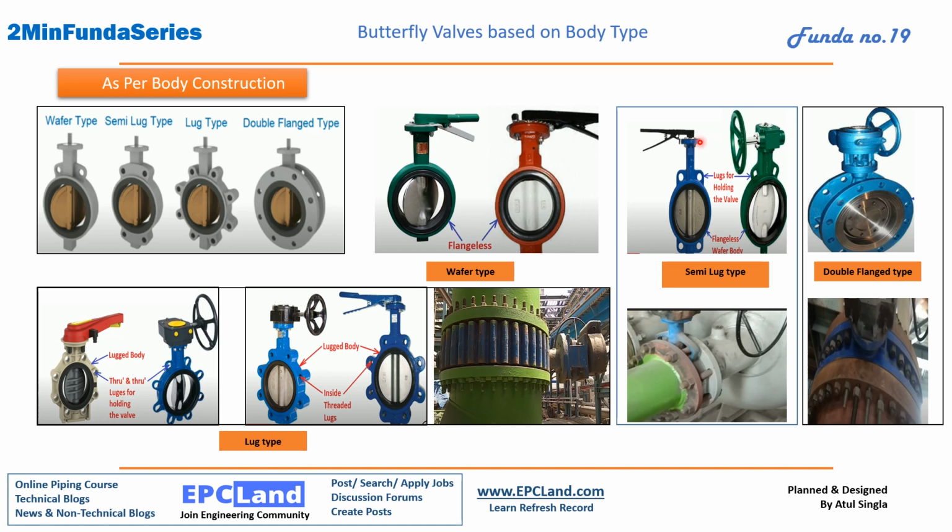If you see this category here, the bolts are moving through the connecting flanges between the lugs. If you unbolt all these studs, then the valve will be removed and these lugs will remain here, so it will be easy to handle. That's why these lugs are provided and we call it semi lug type valve. Then we are having lug type. This was semi lug type, this is lug type. How is it different from semi lug type? We are having lugs all around.